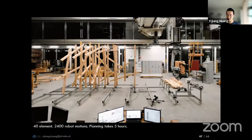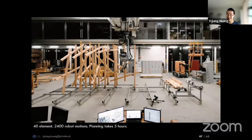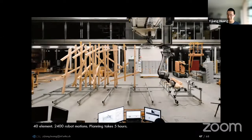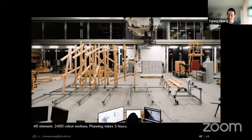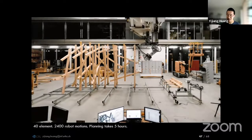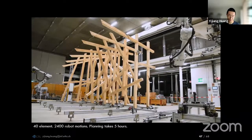So now it's time to see the fruits coming out of our compiler and solver. This timber structure has 40 elements and involves 2,400 robot motions altogether. Planning the entire construction process takes about 5 hours of computing time. As you can see, many of the motions involve operating in a tightly cluttered situation, and our solver is crucial for finding those intricate trajectories.